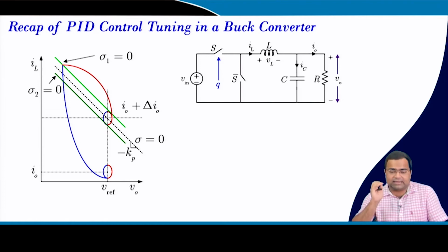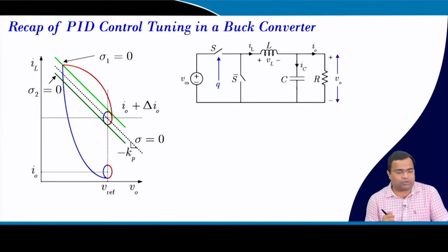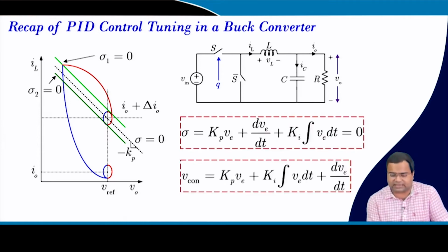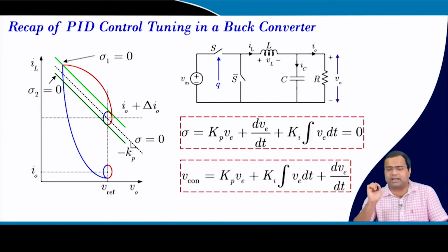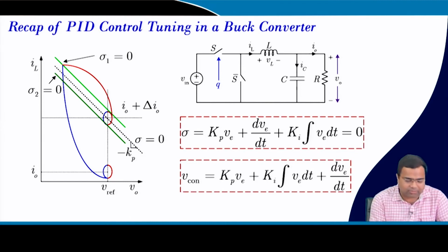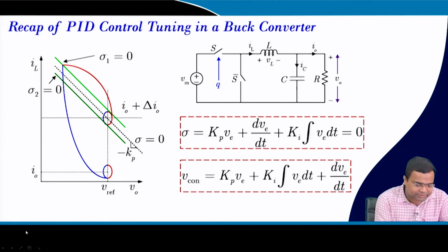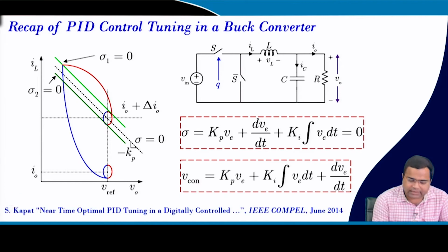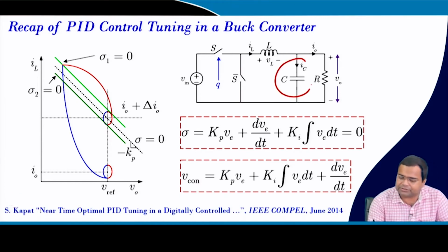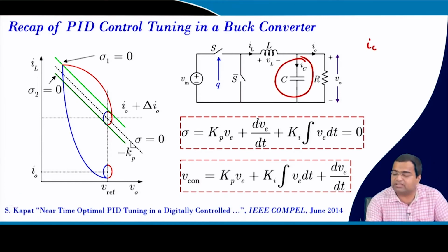In this lecture, we cannot fit in a PD controller in a boost converter because the voltage derivative in a boost converter is discontinuous, right? We have discussed that the PID controller for a buck was straightforward because in a buck converter, if you see the capacitor current IC in continuous conduction mode, it is C dV0/dt in the ideal case.